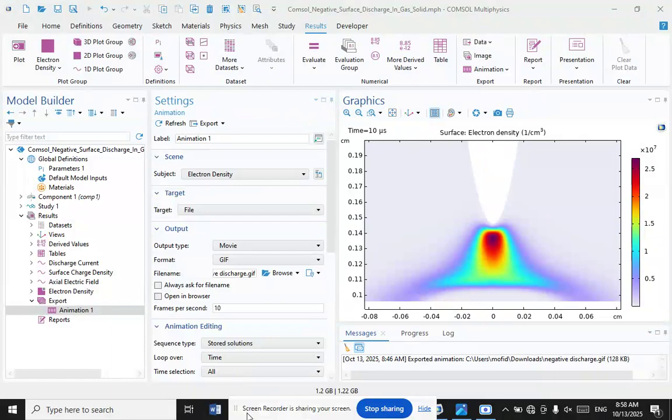The simulation was carried out by measuring the wind velocity and the cleaning efficiency as a function of the device movement speed and the applied voltage level. The results obtained using Algerian Sahara sand dust allowed obtaining an ionic wind velocity of about 2 meters per second and a cleaning efficiency that reaches 95% with a consumed power of about 20 watts.